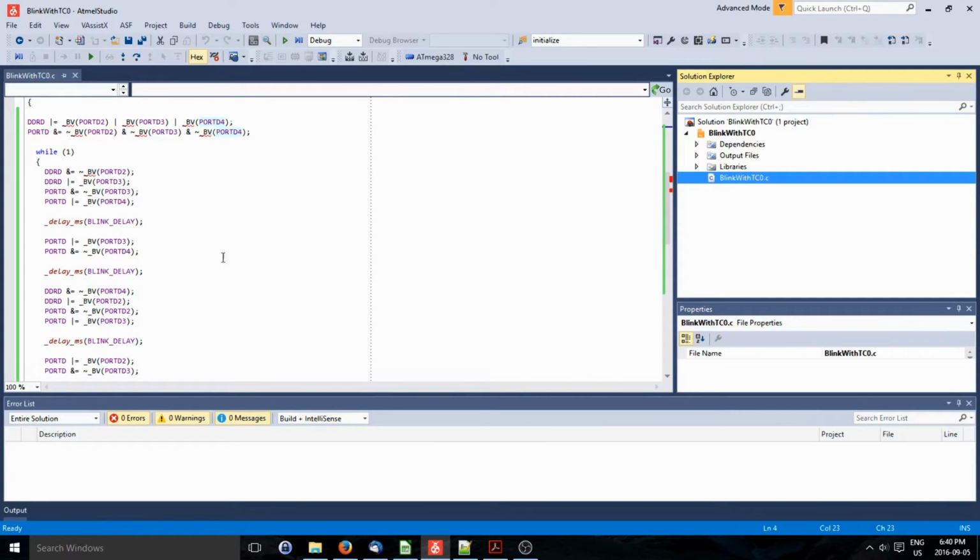And what happens here is in between each setting of turning on or off an LED, we can now run something else instead of wasting our time in delay milliseconds in this function here. But in order to do that, we're going to have to remember what state we are in so that we know where to go next when this process here, blinking the LEDs, starts up again.